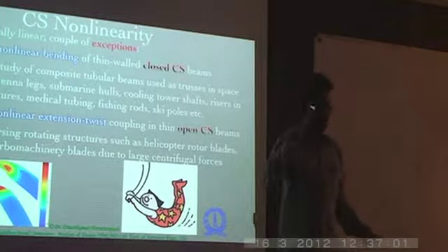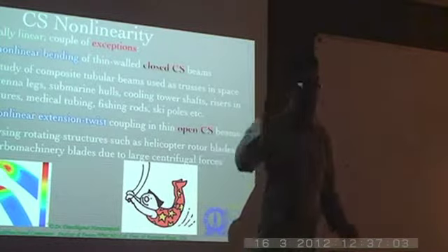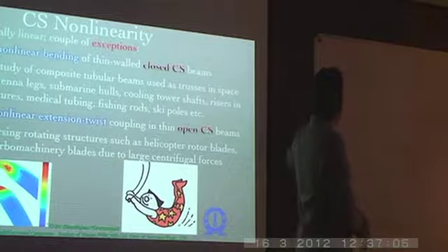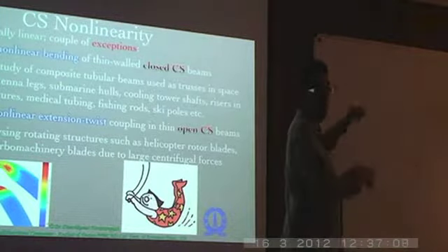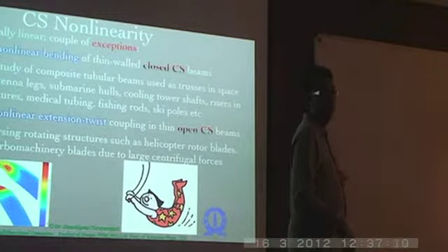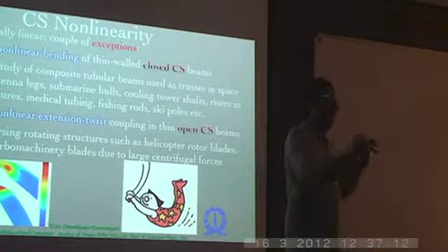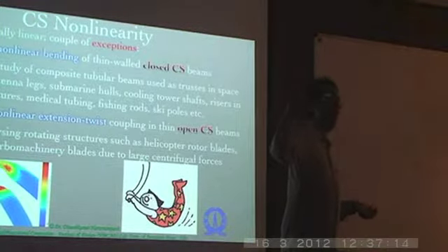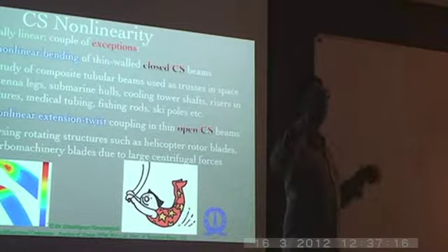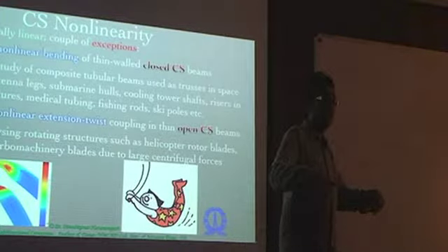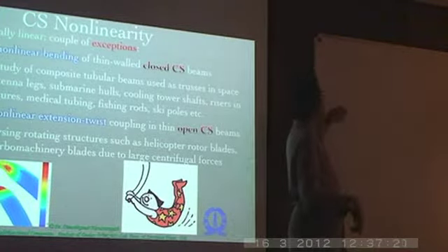See, the cross-section analysis is independent of the loads. So you are getting a general thing irrespective of what kinds of loads you might have. You might have extension, you might have torsion, you might have bending, whatever. So the cross-section analysis is independent of that. So your 1D analysis then will bring in the loading into picture,